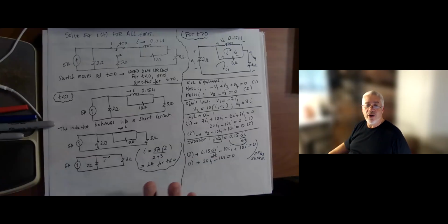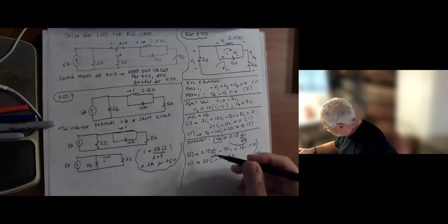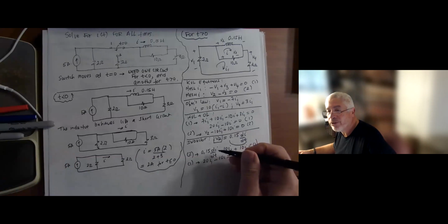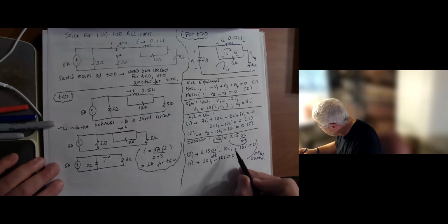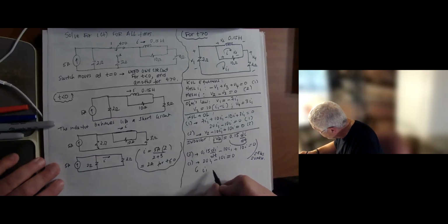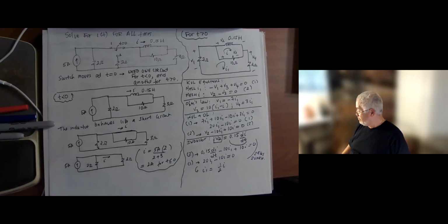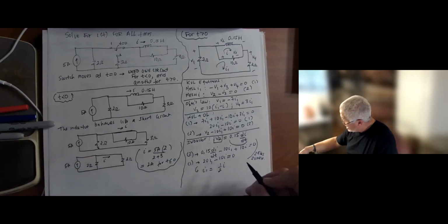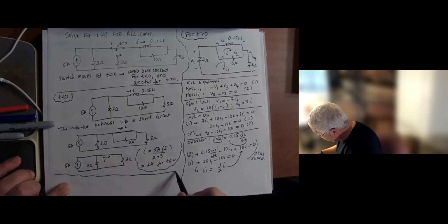Okay. So what we're going to do essentially is solve for one parameter in one equation and substitute in the other one. You don't want to solve for a parameter that's sitting inside of a derivative. So I could solve for I1 here and use I1 here. Let me do that. So here I'm going to say I1 is what? Is 1/2 I. Just solving for I1 from equation 1, and then I'm going to use that in equation 2.